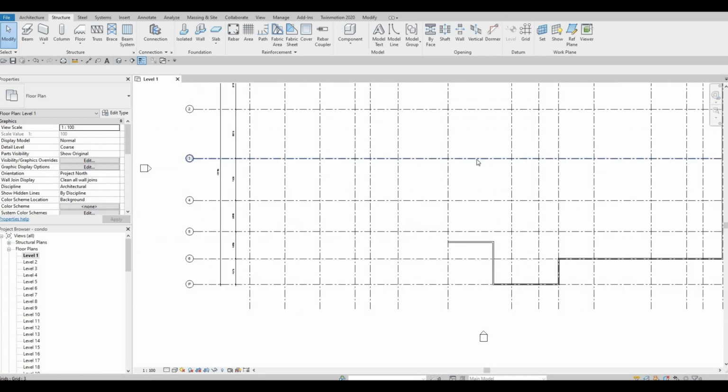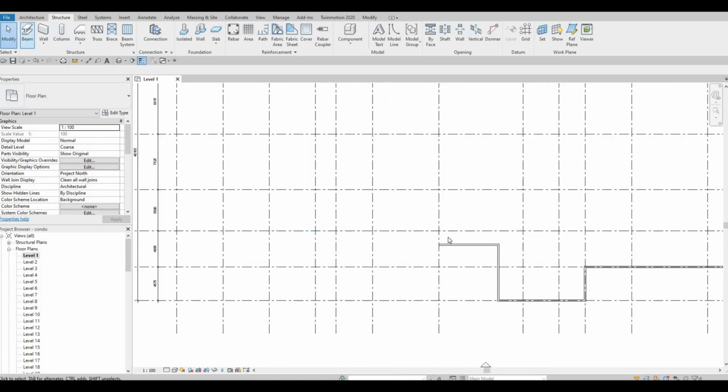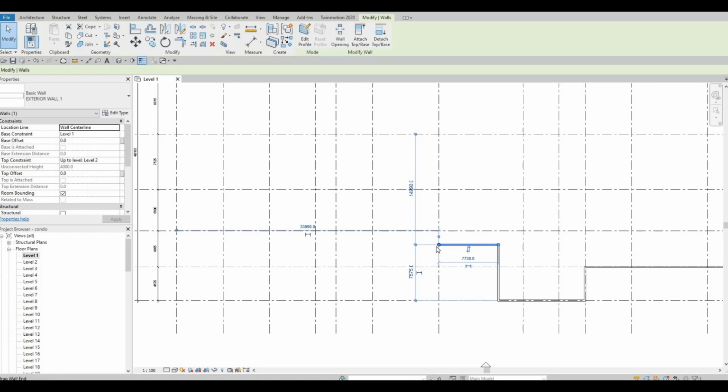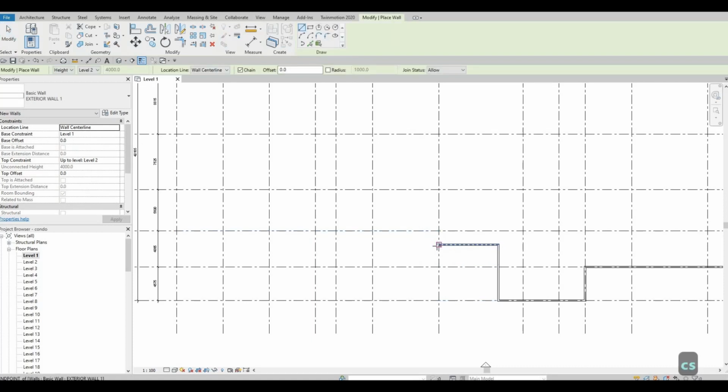This will be the receiving area, so we're just going to give it a quick slant. We could just click here and then CS, which is create similar. That's the easiest and fastest way for you to use the same object or system again. So this is wall system, so we could just use it again. If you have objects or families, you can reuse them as well.